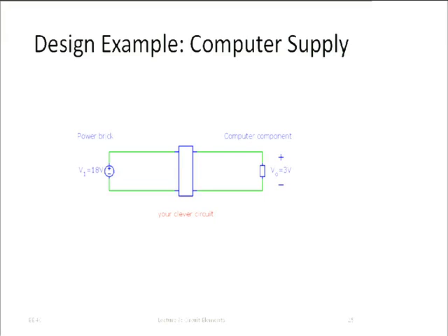Now here we need your clever circuit that somehow miraculously takes 18 volts and out comes 3 volts. How could you do this? Any ideas? Yes. Okay, a Zener diode. Well, we haven't talked about Zener diodes yet. You could do that. Just a Zener diode actually wouldn't be quite good enough, right? We need another, yes? Or you can put two resistors in series, and one is 3 ohm and the other is 15 ohm, and then you put the V naught in parallel with the brick. Perfect. So one thing is you could use 2 resistors in series.